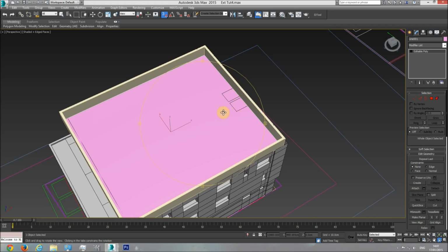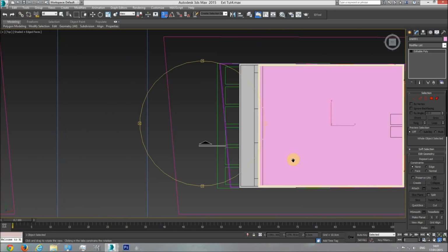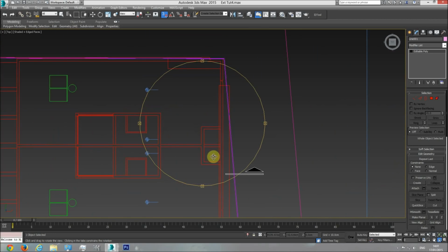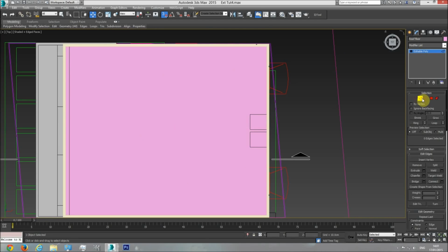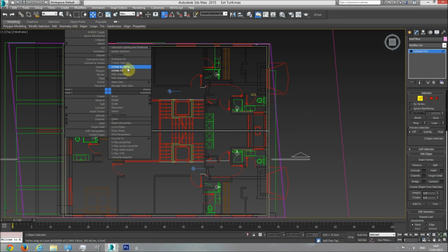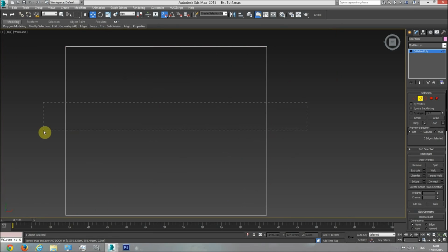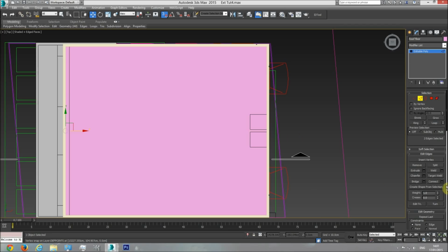There are two holes that need to be here at the drying area. Because as you can see in our plan, there are holes here. So I need to place holes, openings here. So I'm going to take this roof floor and select this edge and this edge. If I hide unselected, I can see I'm going to select 1, 2 edges, and I'm going to connect them.